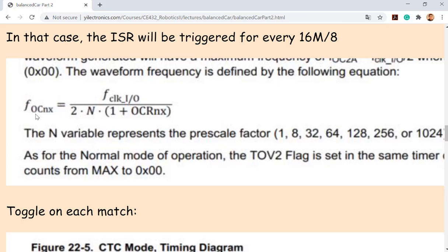So the loop is 4 milliseconds. We did a calculation. Just look at the notes on video, okay, on Wednesday. The way we made 4 milliseconds for the loop is we have a loop timer variable and microseconds function, right? We directly plus 4,000 microseconds to set up the standard loop time to be 4 milliseconds. So the loop will be 4 milliseconds. And we are defining the ISR's frequency is 1 over 20 microseconds, which means every 20 microseconds, it's going to go to the ISR and do something.